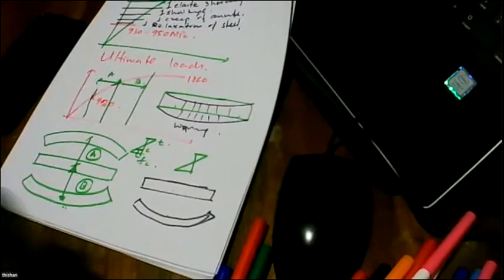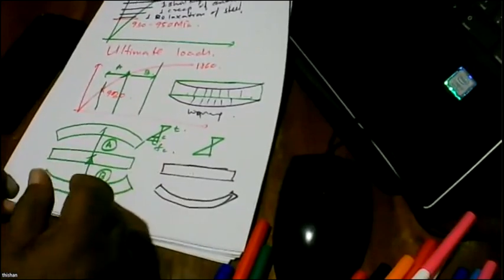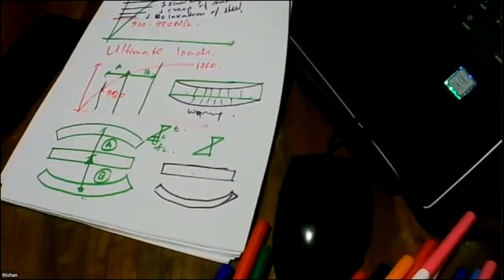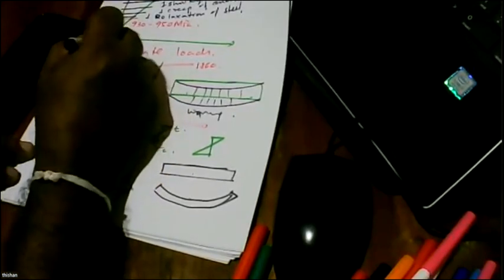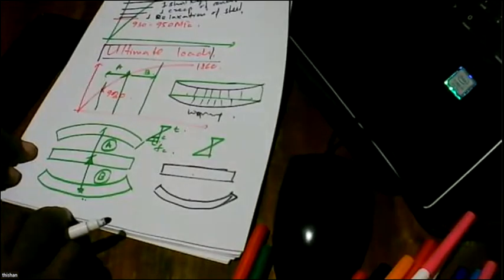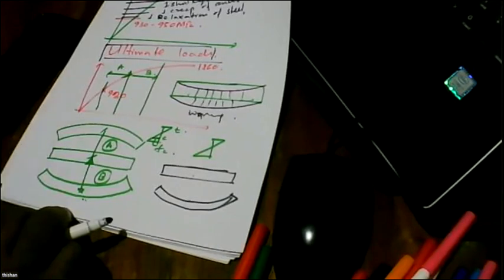Because of that, we end up with a huge advantage in this situation, and these beams generally do not fail in ultimate loads easily. If they ever do, it could be a service condition. But if you have properly designed the beam for the service condition, most of the time you will find that the ultimate loads can be easily taken by prestressed concrete beams.